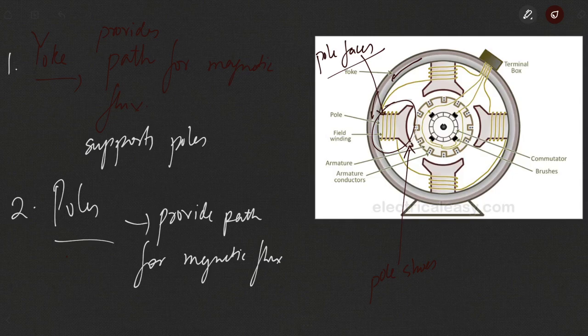and once the current flows through these field windings, they will produce the electromagnetic field. So we actually have electromagnets instead of normal magnets in larger DC machines. In small DC machines that you may have seen in small toys or cars, you have seen magnets placed in the DC motor. But in larger, high-rating DC machines, we do not use magnets, we use electromagnets. For that we use field windings that are excited by an external DC voltage source.